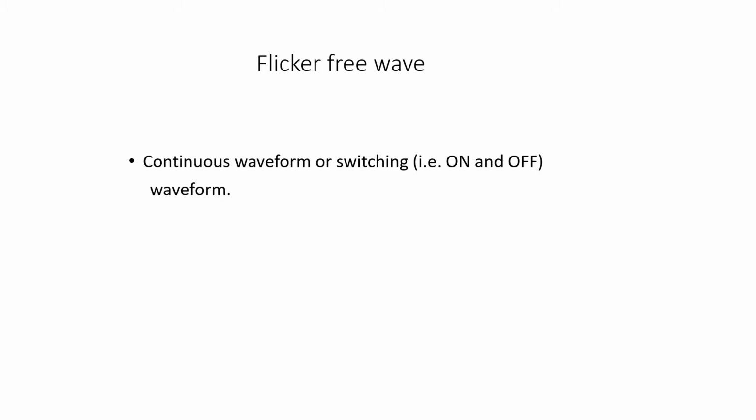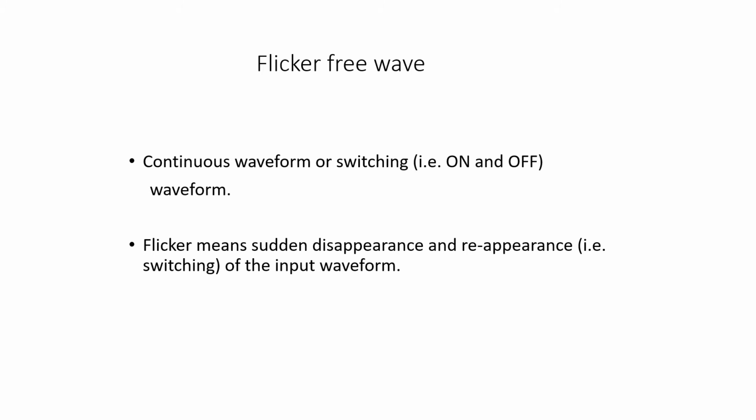So, to brief up, in order to deflect the beam horizontally proportional to time, a voltage is needed which rises linearly with time, which is known as the time-based voltage, which is used to control the position of the light spot on the screen in X direction.